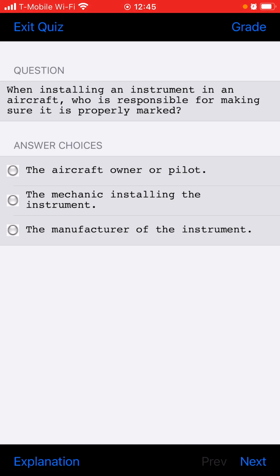What should be done when making bonding or grounding connections between dissimilar materials? The use of a suitable washer so that any corrosion will occur on the washer. What should be done when making bonding or grounding connections between dissimilar materials? Use a washer.